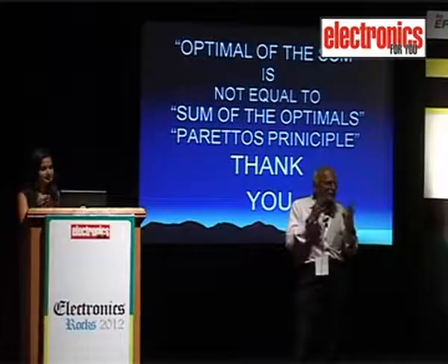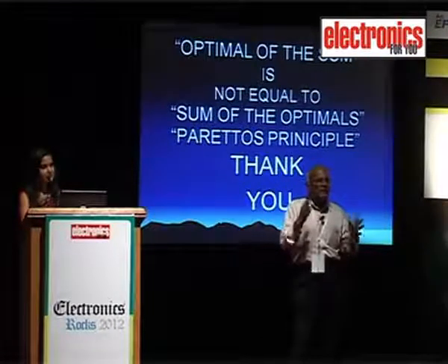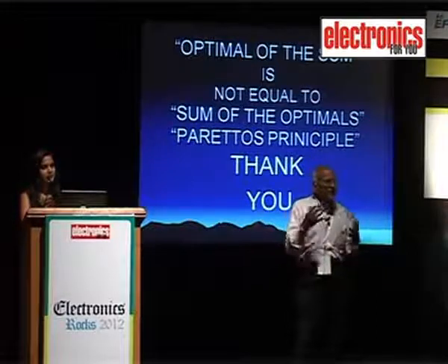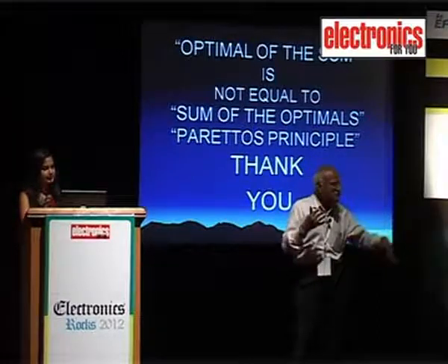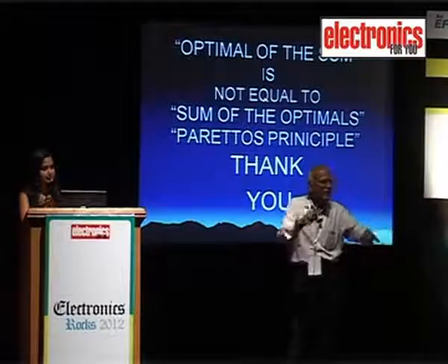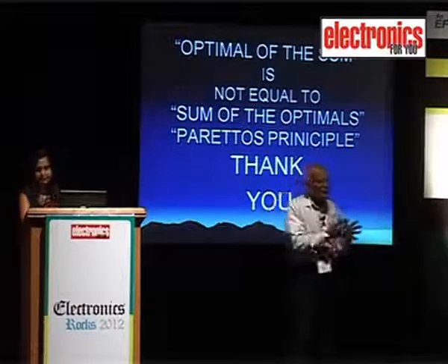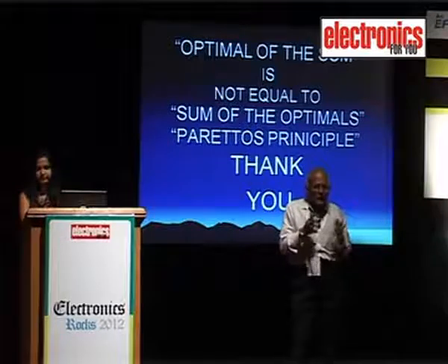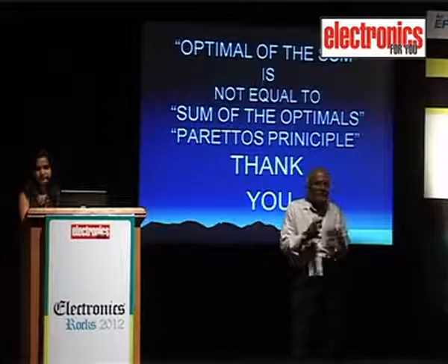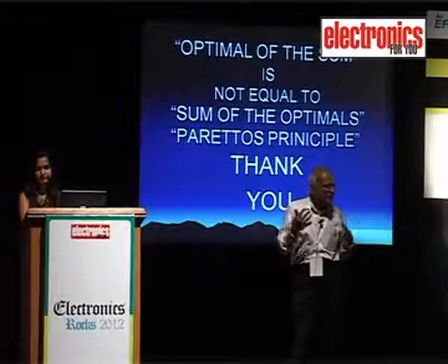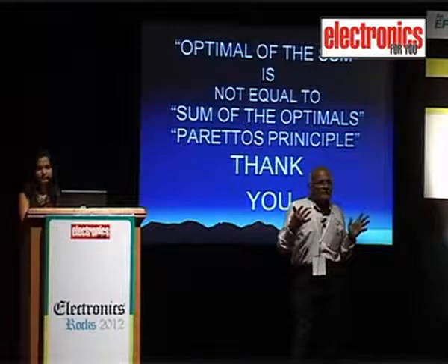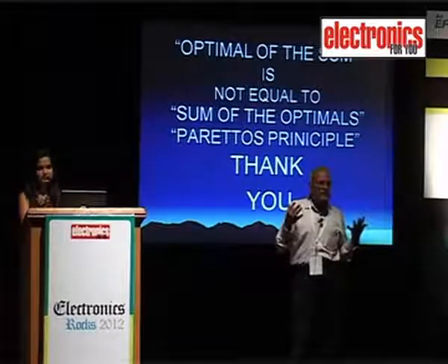Please bear in mind when you're trying to do your optimization, because most of you as designers, at the end of the day when you go to your bosses, they'll say cut cost, reduce the price here, reduce the price here, do this, do that, can you reduce the size of the PCB? The moment you reduce the size of the PCB, you will get into problems of EMI and EMC, which you don't realize. Now today's circuits are working at much higher frequencies.